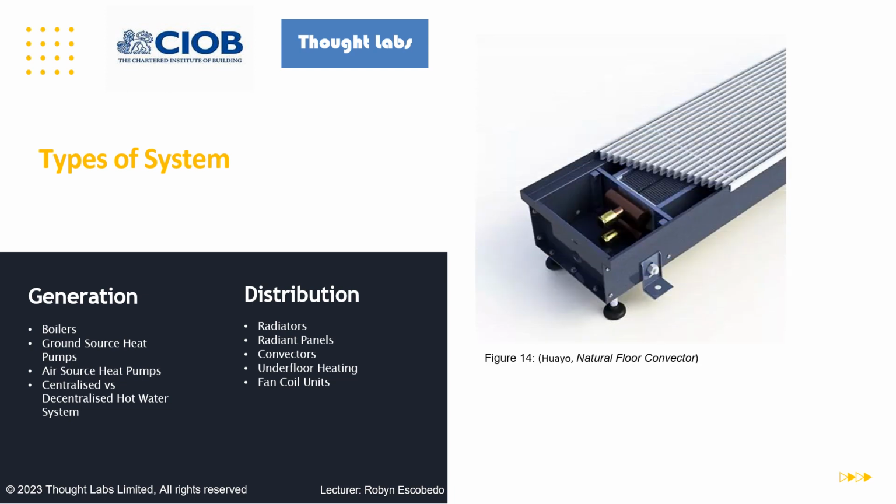Convectors. Convectors can be wall mounted, or like radiators, they can be located in flexible locations, and in the case of the picture in front of you, this is floor trenching. These generally consist of a casing with openings and a hot water pipe. This creates an upward convection current of hot air within the casing. Room air is pulled in at low temperature and hot air is pushed out the top, where you can see the grill bits. An advantage of them is that they provide a high heat output per unit and have a warm-up time faster than radiators.